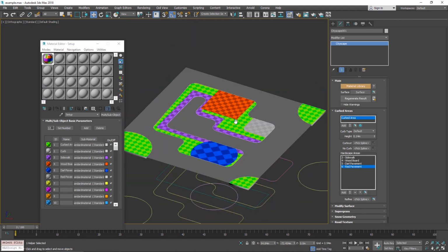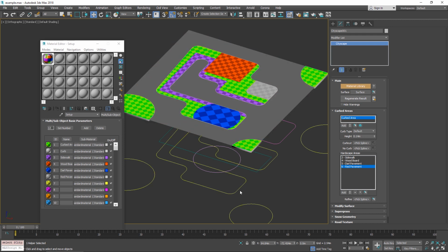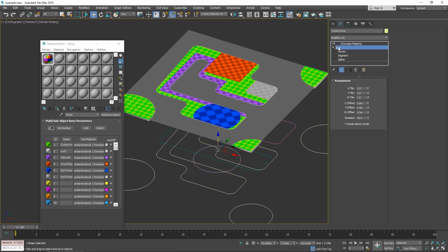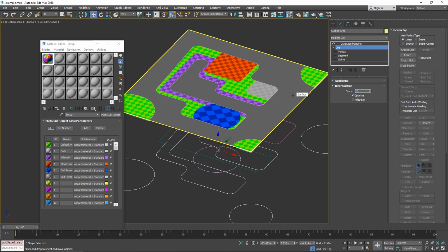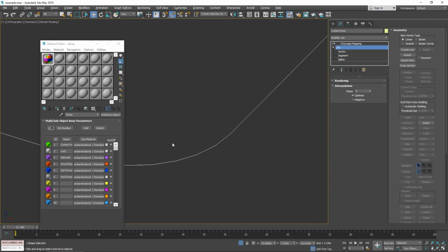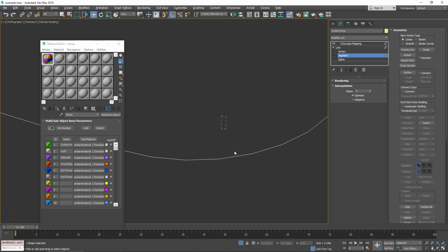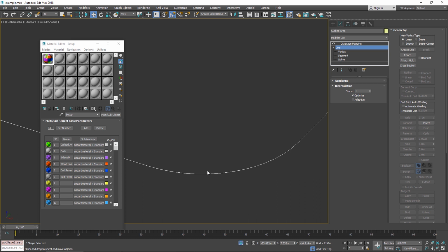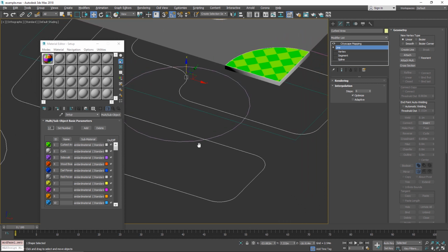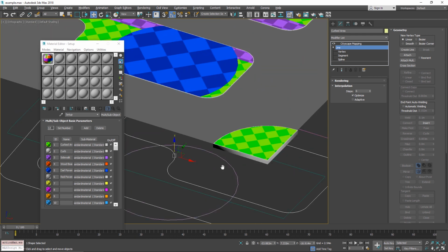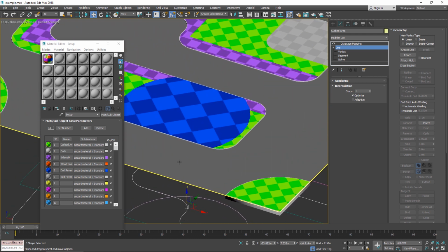Or the other way, which is the preferable way, is to keep the interpolation as low as possible. If you have an area that's visible in rendering and you just want to add more segments on that specific area, you can just divide it. That way you're not increasing the poly count of the overall object and you're just concentrating on this small area. Generally, it's recommended to keep the vertices as low as possible. This will speed up calculations.